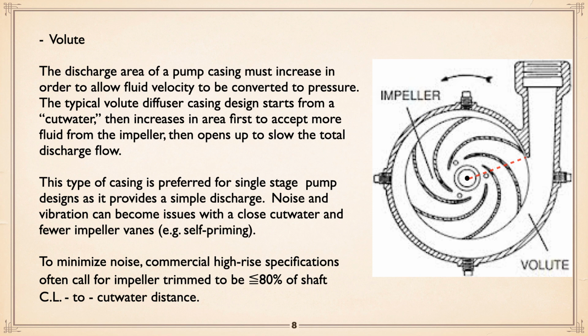And you can see how the casing area increases as it goes around, which not only picks up water but causes the flow rate to slow. One of the interesting things about this is the closeness of the cutwater to the vanes of the impeller. If it's really close and you have few vanes, then you're going to get noise. It's just inherent in the animal.